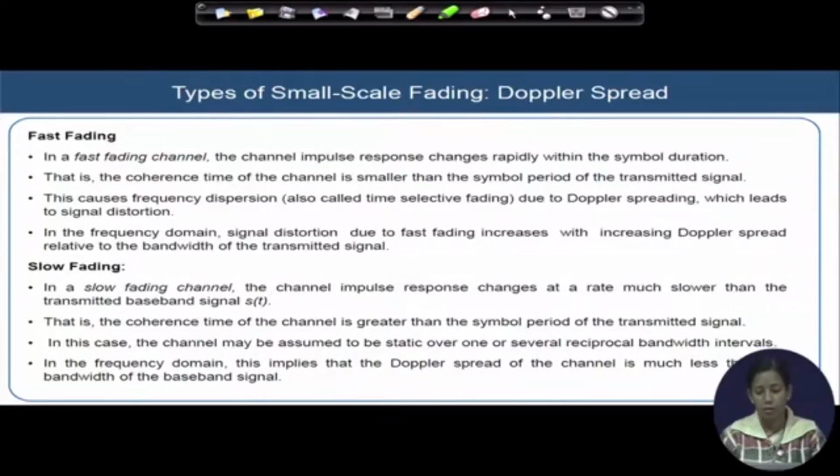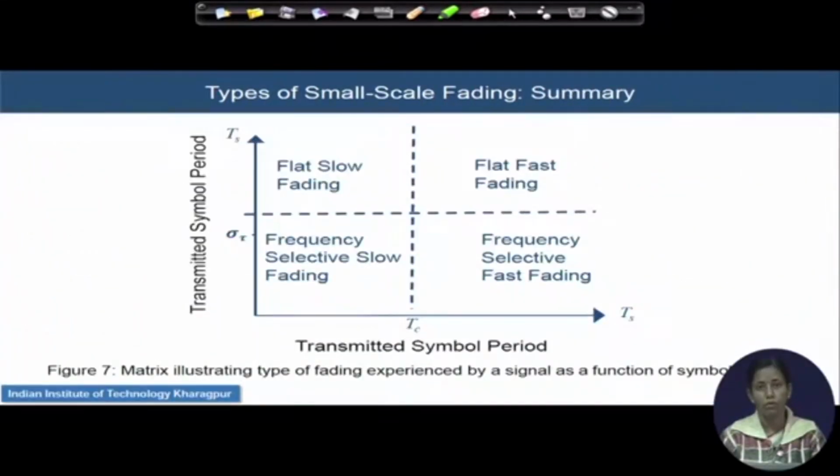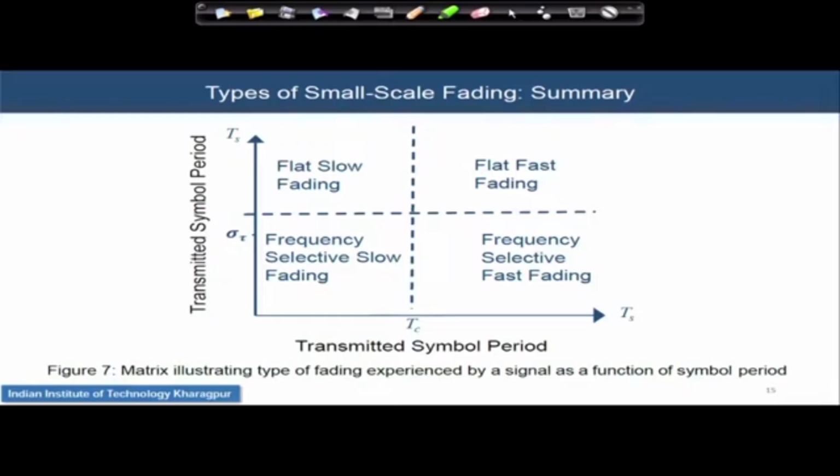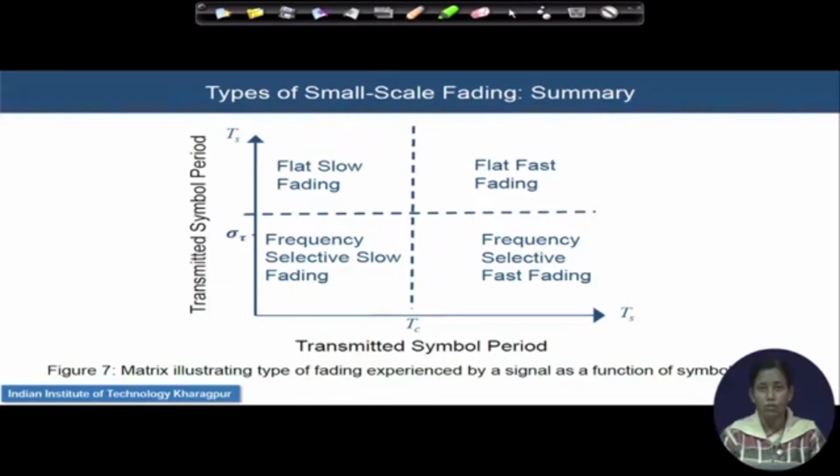Opposite to that is slow fading. If you are moving at a moderate speed or a very slow speed, or at pedestrian speed, here you are going to see a large coherence time over which the channel is showing a constant effect, and you are not going to see a large amount of changes in the received signal's profile. And hence the processing and the corrections due to the fading are less loaded. I mean, the receiver processing will be less loaded in such a situation.